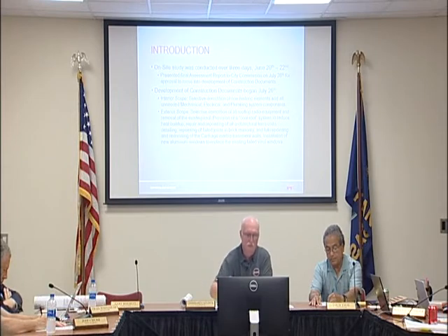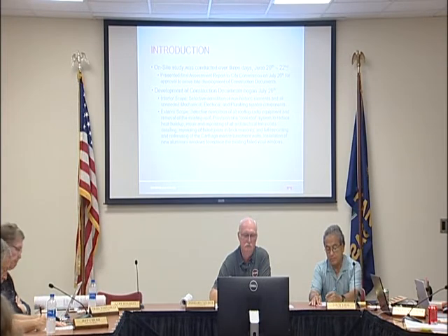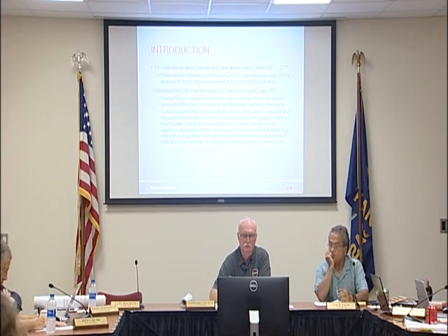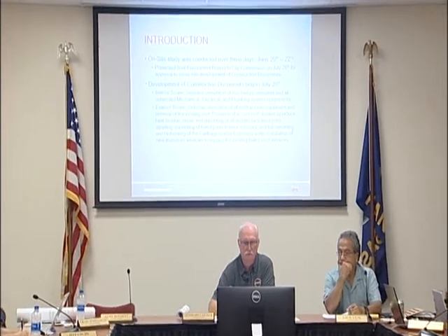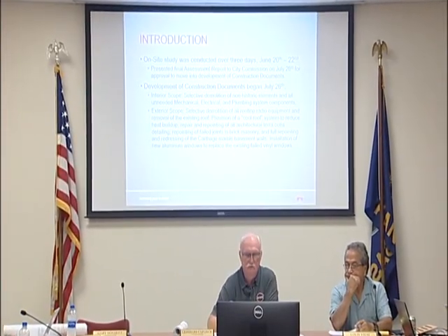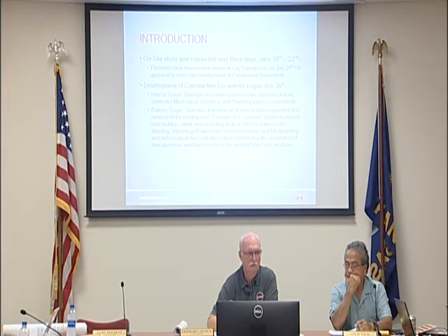For the exterior scope, that includes selective demolition of all of the rooftop radio equipment and removal of the existing roof, provision of a cool roof system to reduce heat buildup with the new roof that goes back, repair and repointing of all the architectural terracotta detailing on the building, repointing of all the failed and open joints in the brick masonry, and full repointing and redressing of the Carthage marble basement walls, as well as installation of new aluminum windows to replace the existing failed vinyl windows.